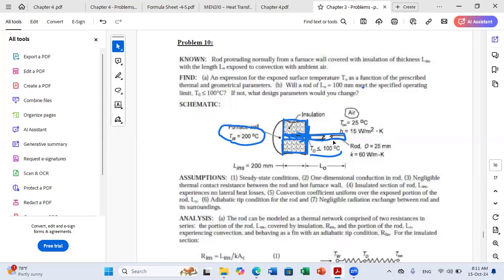So in general, the larger L0 is, the better, until a certain limit. If you remember, we studied the solution for an insulated tip. For a very long fin, we said we can consider a certain equation, but if the tip is not insulated, we consider another equation, the one including tanh. We can look at which lengths will behave as an infinitely long fin.